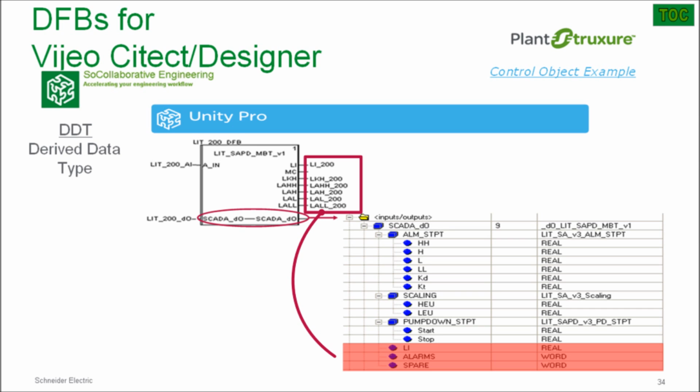I also want to point out that for this OFS OPC version of the DFB, its DDT variables specifically will require locating, assigned an address, because the data contained in it must be retentive. Set points and other similar dynamic, adjustable, or calculated cumulative data like flow totalization or motor runtimes always fall into the retentive data category. One could argue that it is better to leave these DDT elements and the supporting DFB code in place and only manage one version of the DFB.